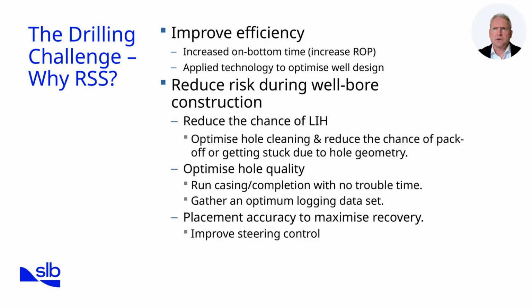Spiraling and micro doglegs from motor assemblies create ledges and cutting beds, raising the risk of pack-offs and stuck pipe, while increasing the possibility of lost in hole. By delivering smoother, more consistent boreholes, RSS reduces these risks. Well placement is also improved.